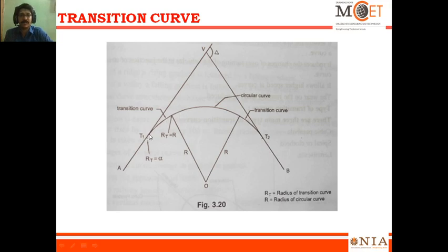That super elevation portion totally depends upon the transition curve part, right? So this portion alone is the true transition curve, and it will be raised. If it is a right-handed curve, the left side of the road will get raised. Here it is the same, right-handed, right? From here, if you see, it is left-handed, meaning the opposite way, right?